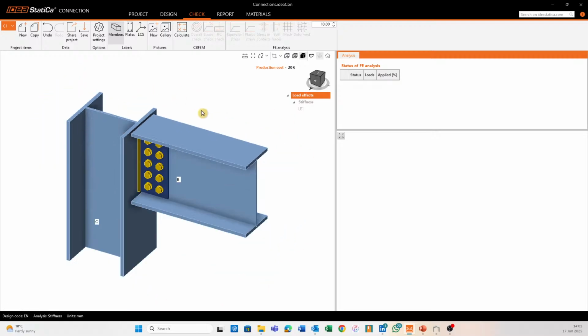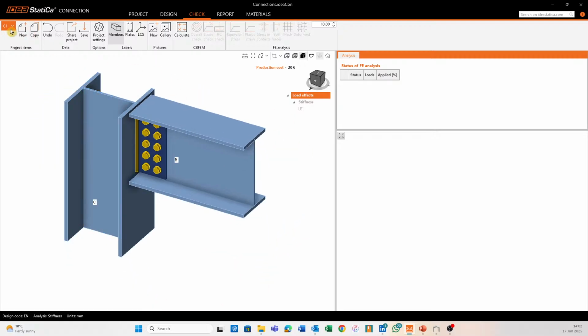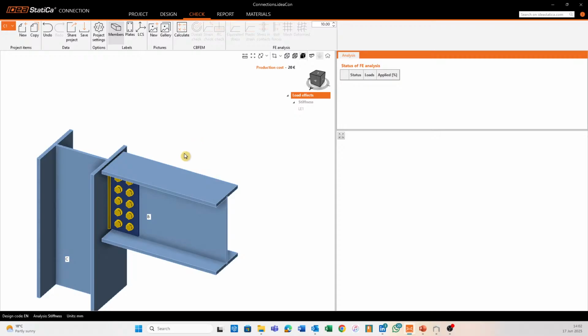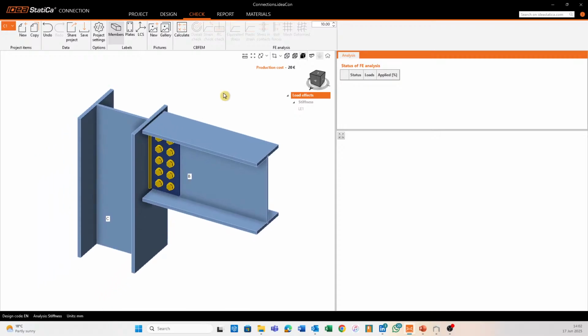We will just look a bit at stiffness analyses. All right, so we've got 4 connections modeled here, and any connection has an actual, so a real life, stiffness, right? If you think of shear plates, fin plates, end plates, we tend to see them as pinned. What we assume with something being pinned, of course, is that it doesn't translate any rotational forces, which means the actual beam has to absorb all of those moment forces, which results, of course, in a larger beam.